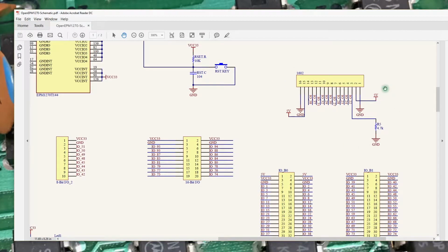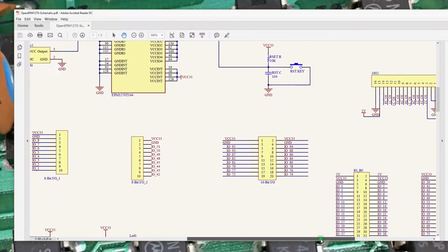There's a connector on the left-hand side of the board that is a 16-pin single inline connector, and this is used for plugging a standard LCD interface down into. You can put a 2-line, 40 character, whatever you want, LCD display plugged down in there. It's got power pins to pick up power for the device and for the backlight. And I believe this resistor here is used to set contrast. It's fixed, and it's driven from this set of IO pins. If you've dealt with LCDs like this, there's typically a parallel interface, and you're sending information to it and then clocking it in.